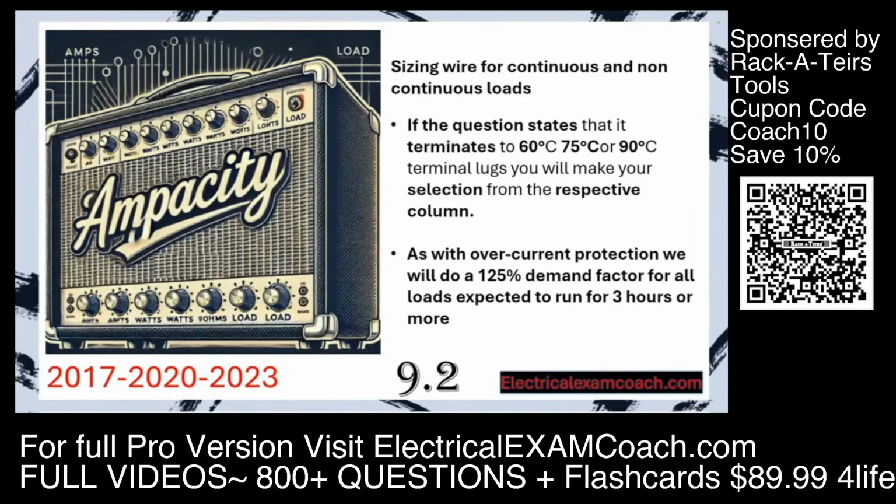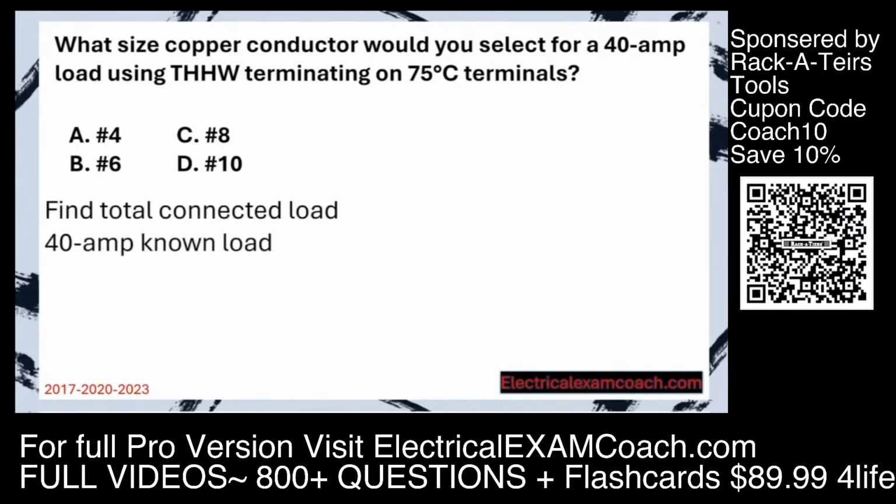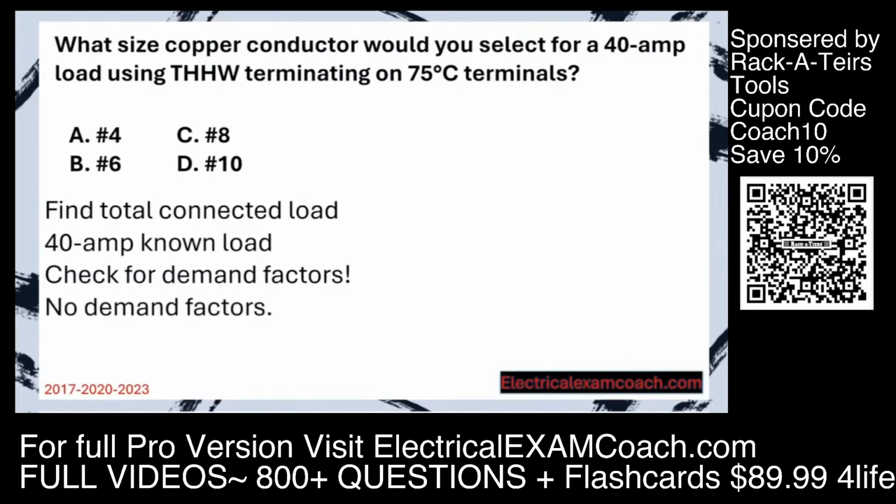Let's get to it. What size copper conductor would you select for a 40 amp load using THHW terminating on 75°C terminals? Step 1, find the total connected load. In this case, we know the load, it's 40 amps, but we must check for demand factors. It doesn't mention a specific type of equipment or that it's going to be a continuous load, so in this case, there are no demand factors. And we always have to remember that all wire must meet or exceed the known load. So we have to find a wire that meets or exceeds 40 amps.